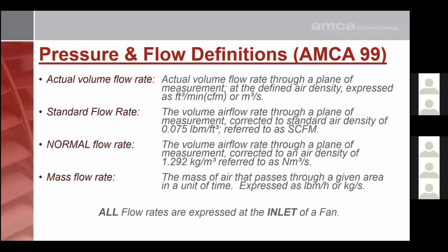A fan, we often talk about actual volume flow rate. A fan is a constant volume device in the sense that a fan of a given size running at a certain speed will always produce the same volume flow rate. The pressure it creates and the power it draws will vary, but the volume flow rate will be the same.